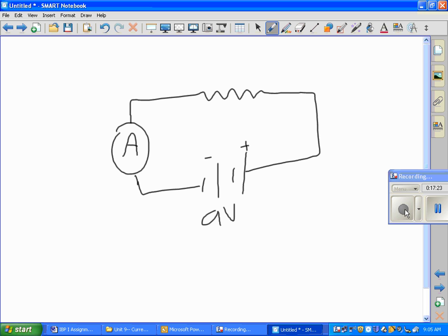As these electrons are flowing along, or as the current's flowing along here, no energy has been used yet. So my electrons, or the charges, would still have 9 volts of potential. The light would be glowing, and the weird thing is, right over here, they would have 0 volts of potential. They would have used 9 volts to make that light. In order to measure that, I take my voltmeter and I place it before and after my device to measure the difference in potential from one location to the next.